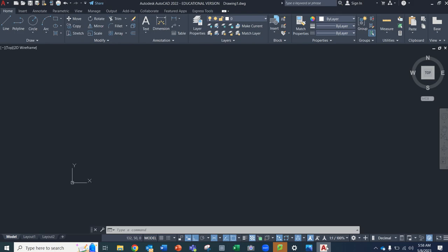So let's go back to CAD. We're going to come up to this little command here, which is going to be an ellipse. We're going to drop down and click elliptical arc. Then we're going to come down to this little bar you have at the bottom in which you can type commands, and click on ISO circle. Then you're going to move your cursor. Ensure that your cursor is somewhere in the middle of your page.